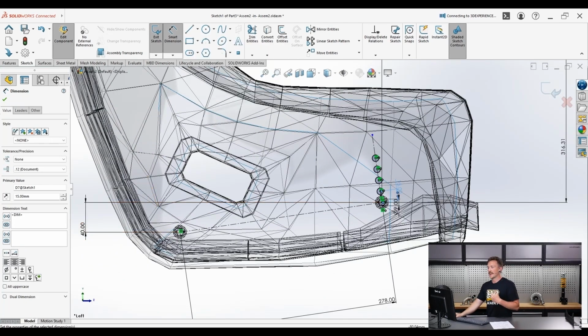So basically we're going to create the holes over here in a bit of an arc, and that arc is going to be taken from the center hole here to basically make sure that any position that we put the seat in on those holes, it's going to fit no matter what. And then it's going to be an arc of those slots patterned up here, but that'll make a bit more sense in just a moment.